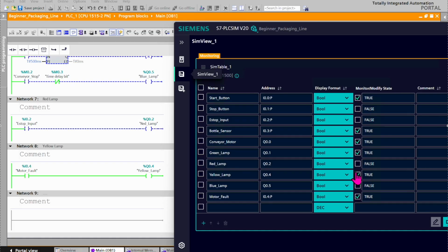In real factories, the stack lights are not just cosmetic, they are part of safety and productivity. Priority matters. Red always overrides green. If a machine is in a stop, it must never look like it's still running. Now our packaging line communicates the state clearly.